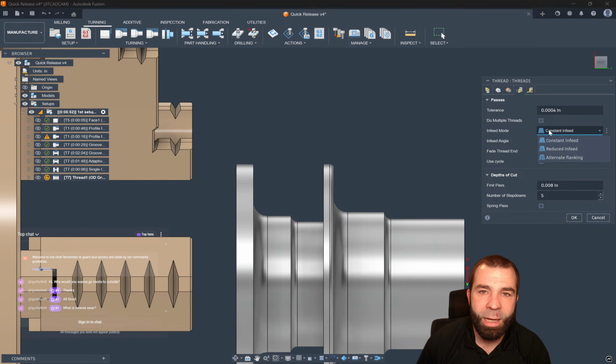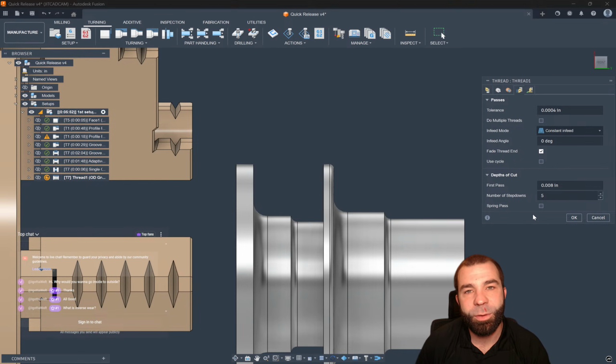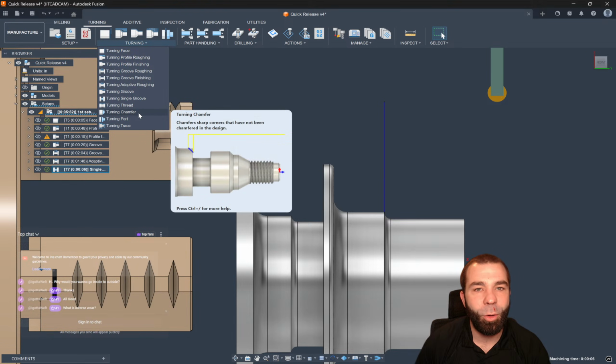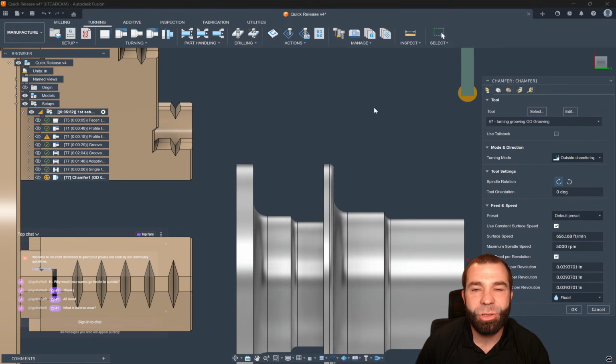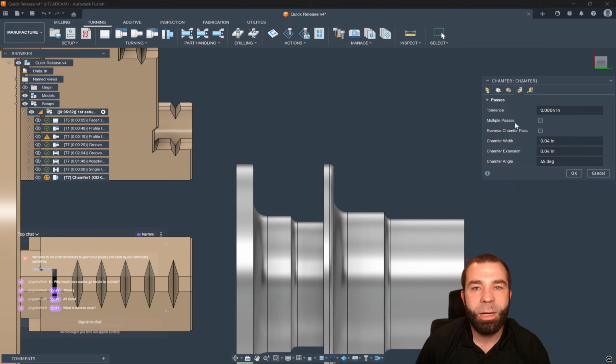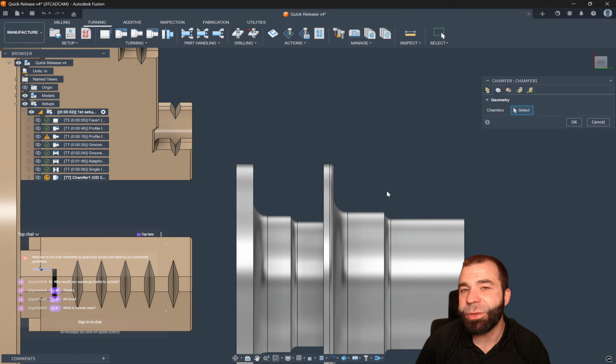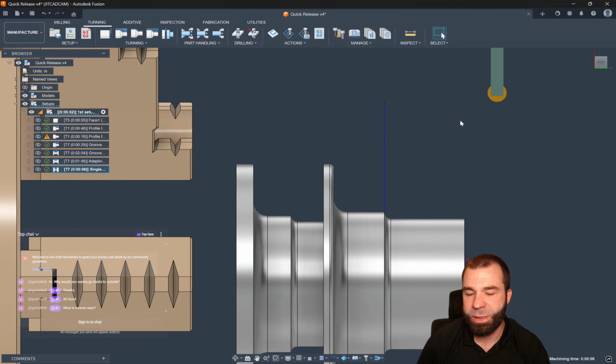Once you get the blue lines, how do you want those blue lines to interact with your part? How do you want to remove the material? What is my depth of cut going to look like? So again, we look at a few more. Chamfer toolpath, again, you're just busting the edges on the part. But again, a very simplified passes menu, as in, do you want to add extensions or do you want to reverse it, make multiple step downs as you cut those chamfered edges off? Again, this is all stuff that I would do at the model level to make your life much easier.